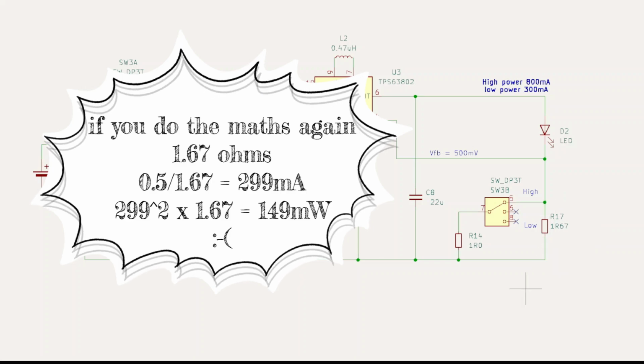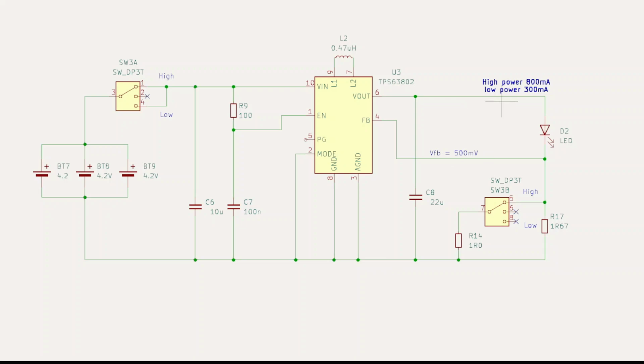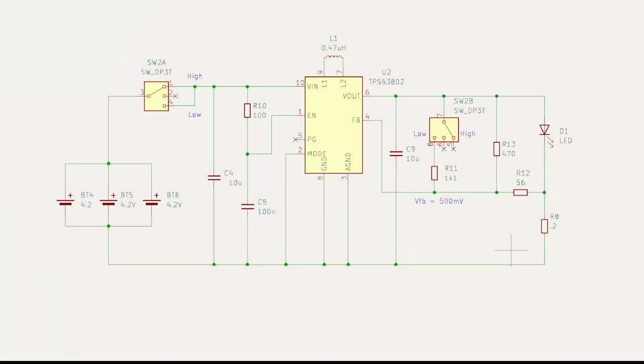So this circuit allows you to keep the brightness constant as the battery voltage changes, but it's still relatively inefficient, because we're still dissipating power in these two sense resistors because they're reasonably high values. So that kind of prompted where I'm going, but again it fell on the toy room floor. Right, this is hardware version, the final cut, so to speak.